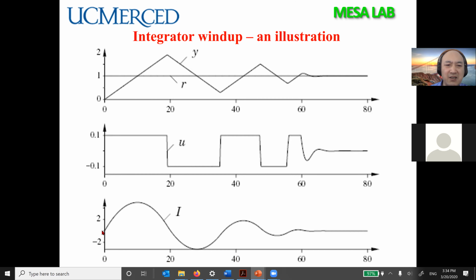So you can see that the system will, because the error is too big, trigger the saturation. The initial error is very big, so it will be saturated. Then this is always above 0.1, right? So you can see that it will continue straight until the point the I goes down, okay?